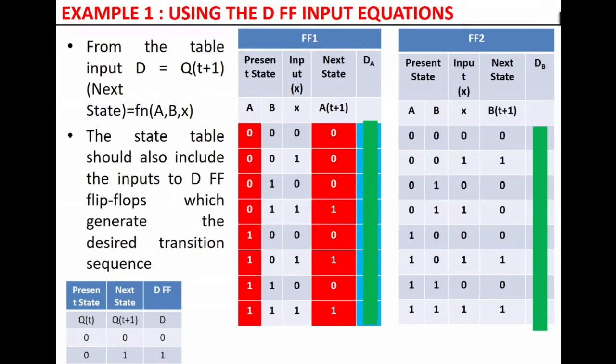Minendle, correct. That is for a D flip-flop. Actually, for the D flip-flop, the input doesn't care about the present state. If you have the next state, it's the input. So if you are using a laptop, you should just cut and paste from somewhere. I'm answering Minendle who has asked. So if the next state is 0, then the input at that should also be 0. What is at D becomes the next state.